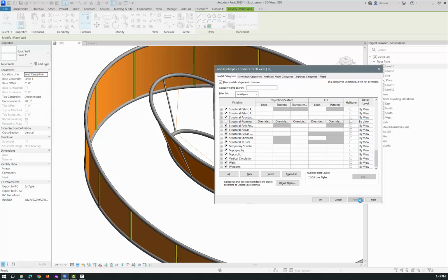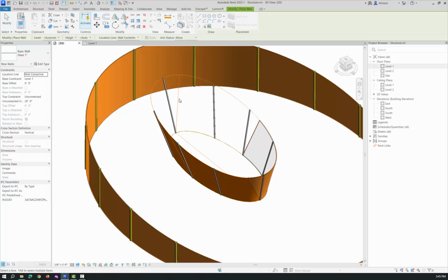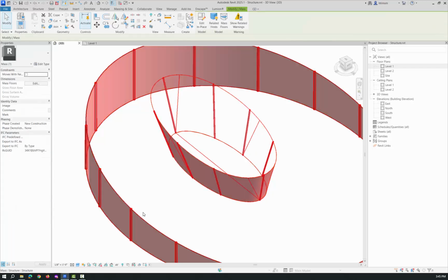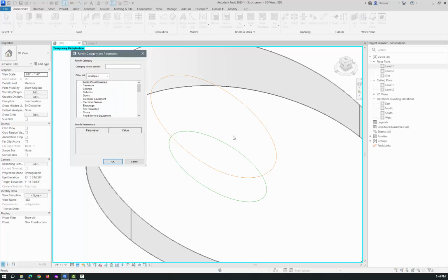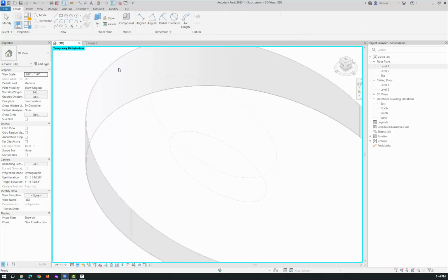And, right, and we do have, and let's, oops, I think I still have some. Let's get rid of that. And maybe let's hide this element. But I do have these two things here that it's possible that if I go to architecture component model in place, let's see if this will work. If I go to mass, click OK, and I'll call this center glass, right?